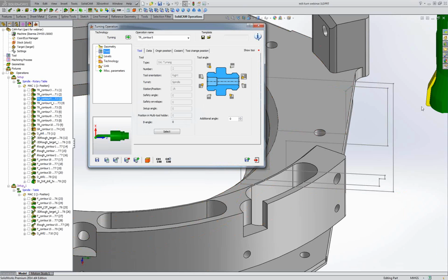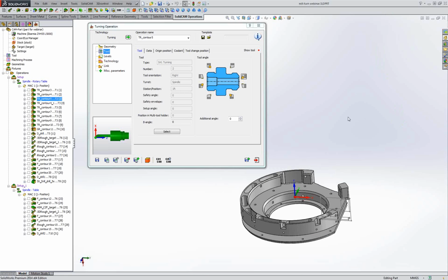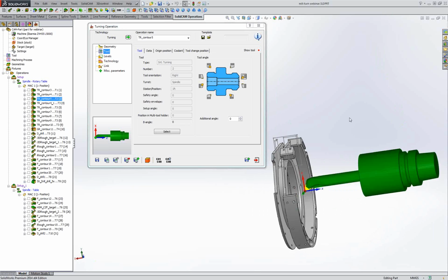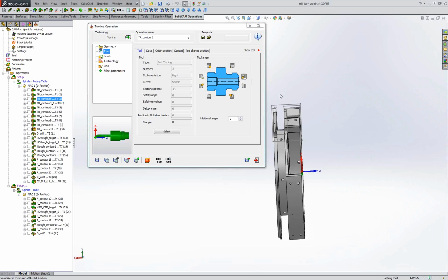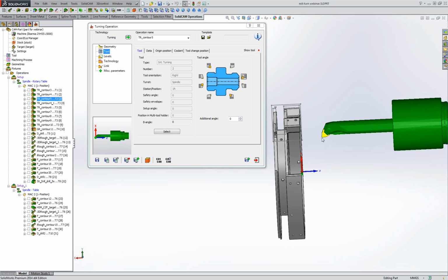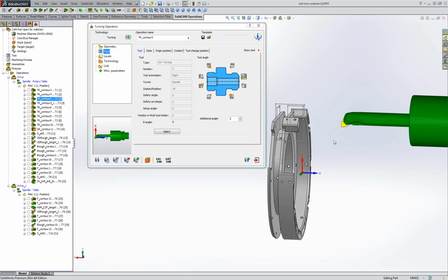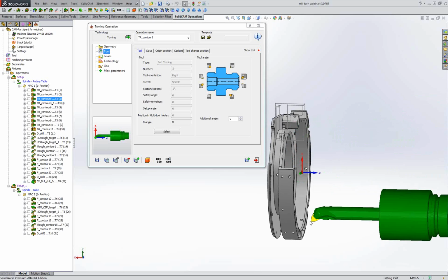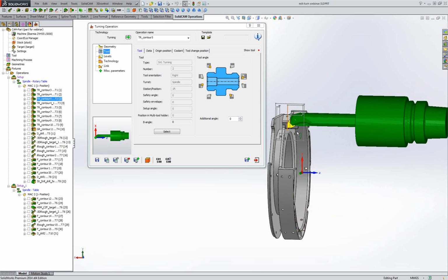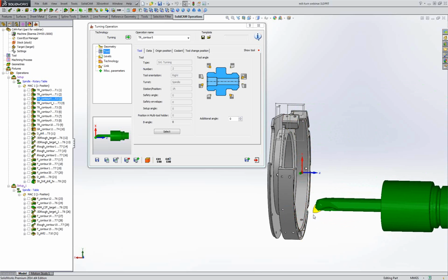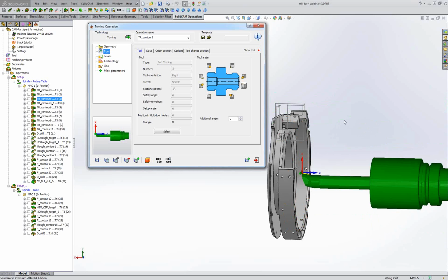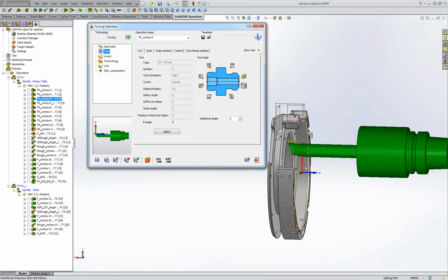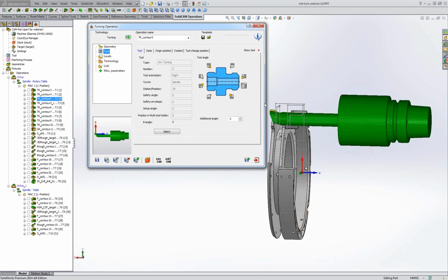Again, I always want to know what is the best position to work with the tool. Rotate the part as in the picture, and the position that I select here is the position of the tool on the part. Why? Because I define here the geometry, yes, but I want to work in the negative side. If I want to work here, I select this position. Now we will have a positive toolpath in X.